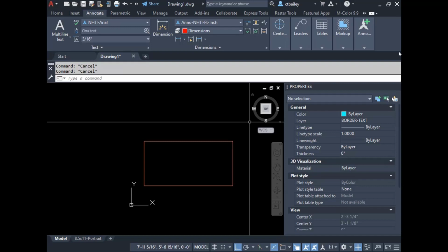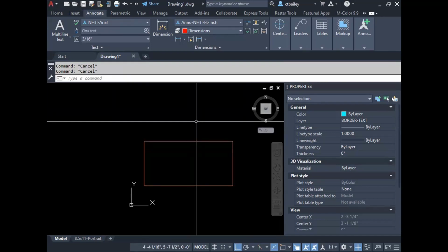So I go to blocks, I have recent blocks, favorite blocks. You have to make your block. Draw something and then convert it to a block. Draw it before you get into the block. Yeah, that is the best way to do it. You may be able to start a block empty, but I don't know how to do that. It's best to start with something, build it into a block, and then edit it from there.